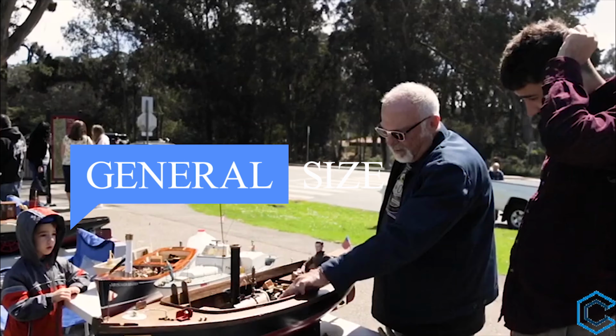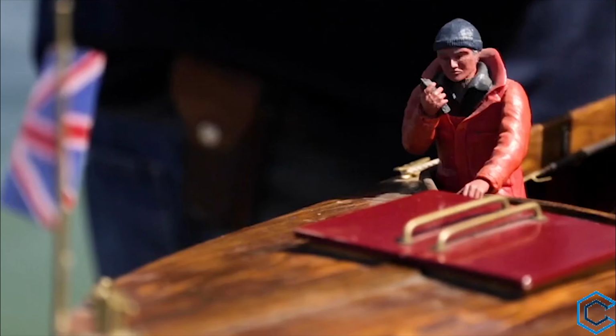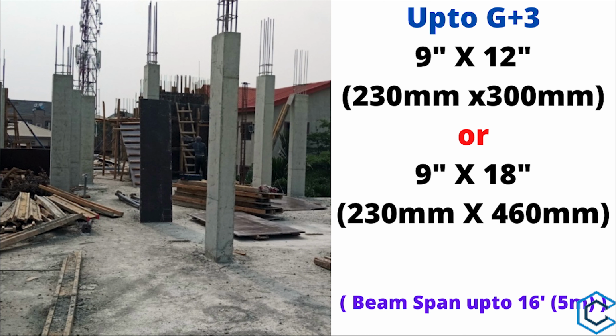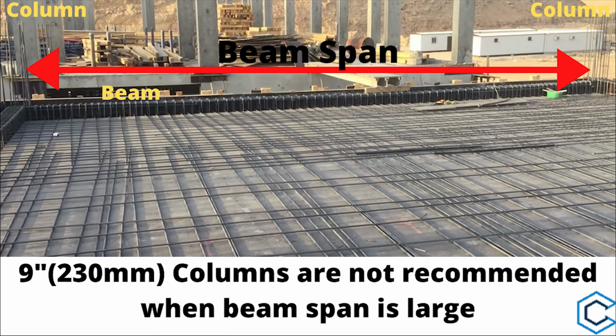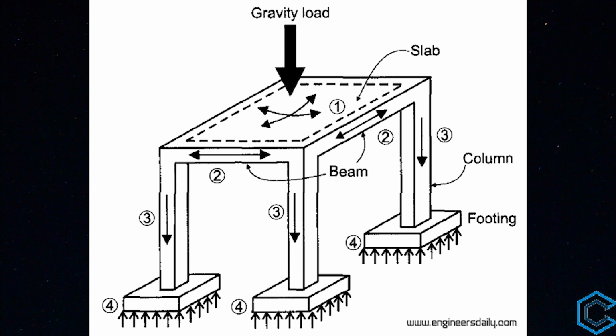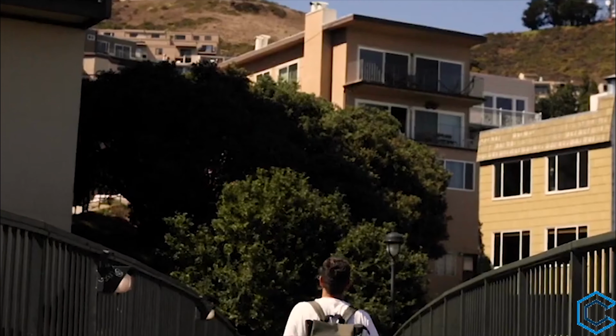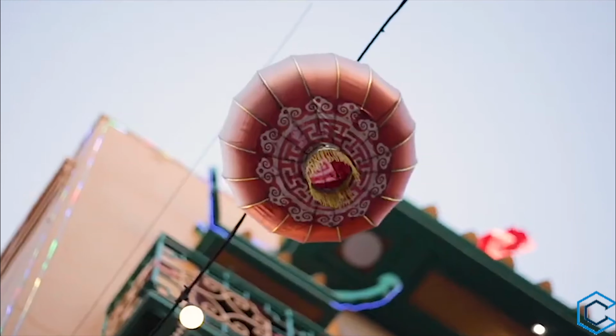Now let's talk about general sizes of columns used in residential buildings, and the maximum and minimum distance criteria between them. For buildings up to G+3, we can use a 9 inches by 12 inches column or a 9 inches by 18 inches column for buildings having beam span up to 16 feet. Remember that 9 inches columns are not recommended for commercial buildings having large span halls with heavy loadings of goods. Also keep in mind that 9 inches columns are good at taking axial loads, but they are quite weak under bending caused by earthquake and wind loads. So we have to take extra care while using these columns in buildings above G+1 story.